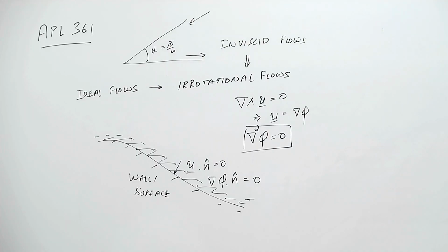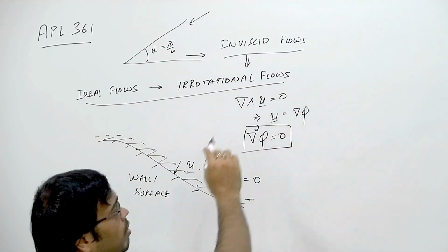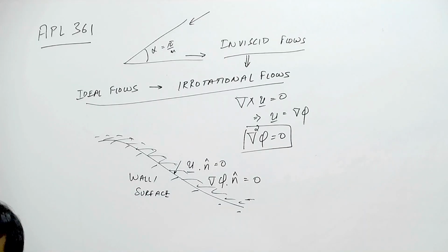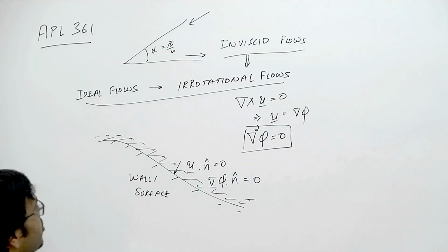okay, which is what we saw from our basic ODE example, that u equals 0 couldn't be satisfied by the outer solution because we obtained all of these equations when we naively dropped the viscous terms. Okay, it is the viscosity which supports that no slip condition. You just dropped the no slip condition because you dropped the viscous terms from your governing equations.